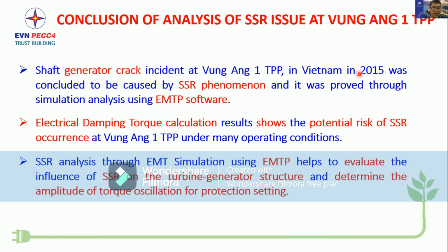And the last conclusion is that SSR analysis through EMT simulation using EMTP helps to evaluate the influence of SSR on the turbine generator structure and determine the amplitude of torque oscillation for protection setting.